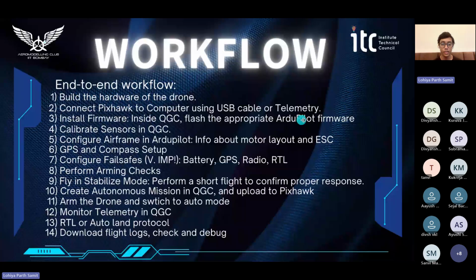We then calibrate the sensors using QGC. And then we use the ArduPilot software to configure the airframe. That is, we give ArduPilot the information about the motor layout on the drone and the electronics, that is the ESC, motors, etc. We then calibrate the GPS and compass. Then we configure the fail-safes. That is a very important step. That is, we configure the battery, GPS, radio, and RTL fail-safes at least. And then we perform the arming checks for the drone.